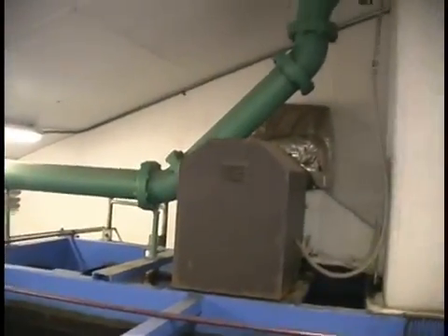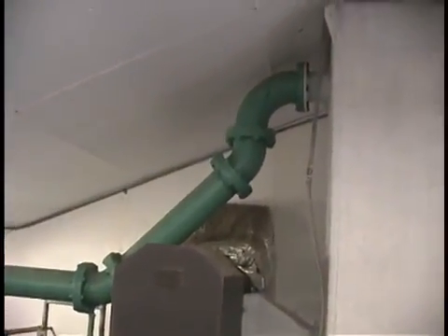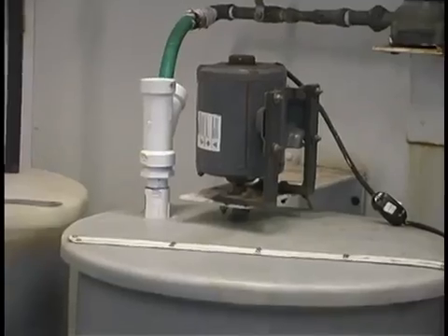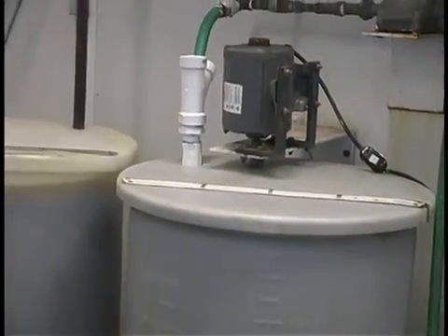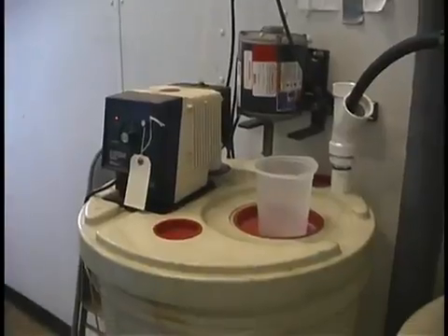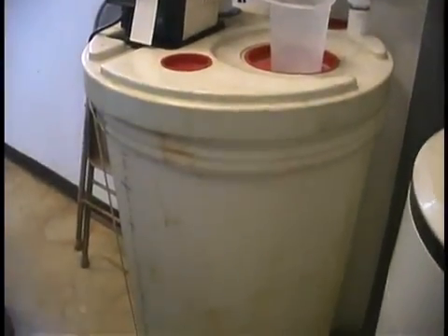Aeration consisting of cascading the water over redwood slats with a counter-current forced air blower for iron oxidation. Potassium permanganate for iron oxidation and regeneration of the filter media. Polymer filter aid addition.